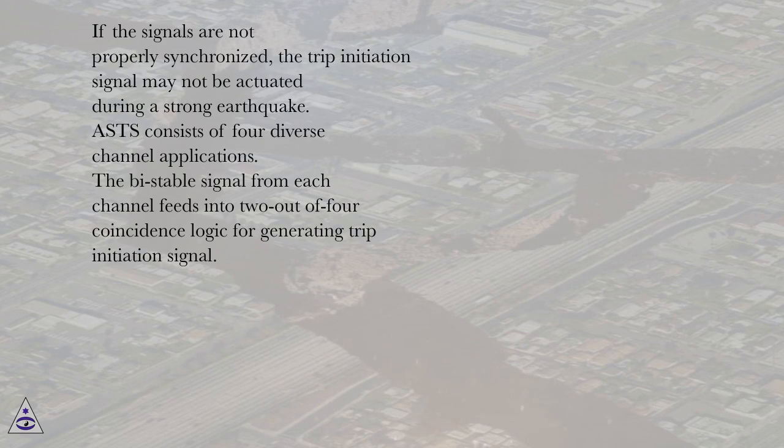ASDS consists of 4 diverse channel applications. The bistable signal from each channel feeds into 2 out of 4 coincidence logic for generating the trip initiation signal.